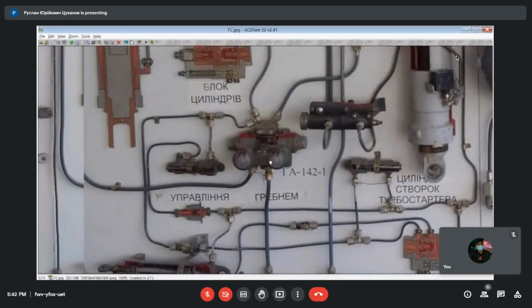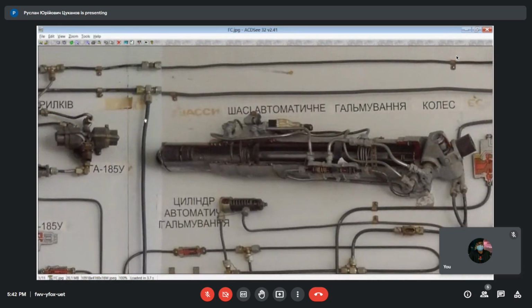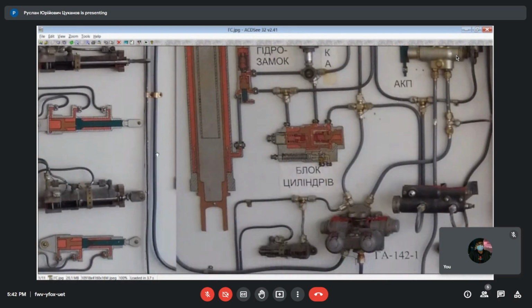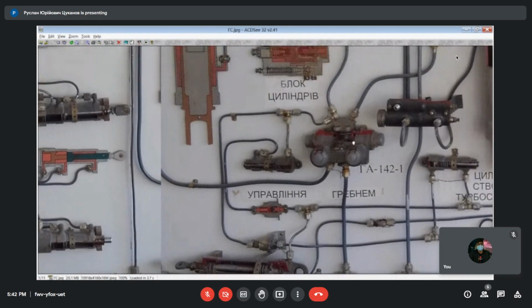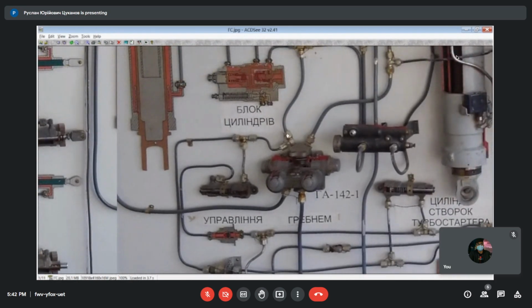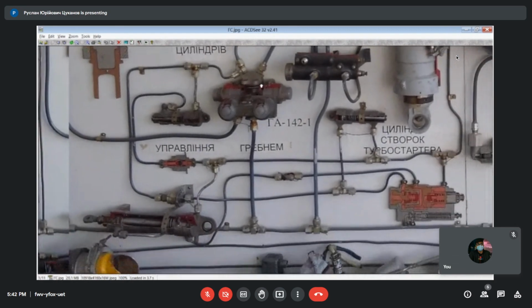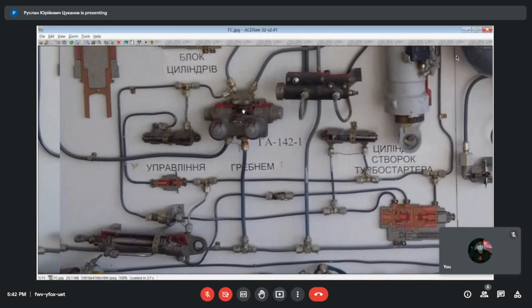So this device is connected to a high pressure line in the top of the combined hydraulic system and also attached to the return line. Outlets, here there are two lines, one for extension, one for retraction. Now we will see what each line is intended for. So the valve can connect pressure line here, return here, or vice versa, or can connect both to return. Normal state, de-energized, is when both internal lines are attached to the return line and the pressure line is blocked.